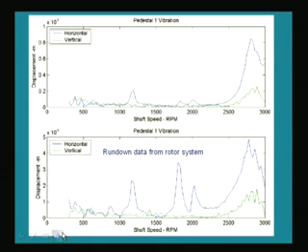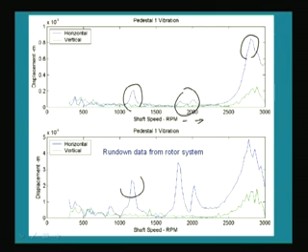This is another signal from a rotor. When we change the speed of the rotor from low speed to upper speed, we are doing some kind of run up of the rotor, and we are trying to find out the amplitude, how it increases. So you can see some peaks appearing there at the natural frequency of the system, or the resonance conditions are there. Here also you can see some resonance conditions. You can see there is a 1-to-1 matching. These are the critical speeds of the rotor.